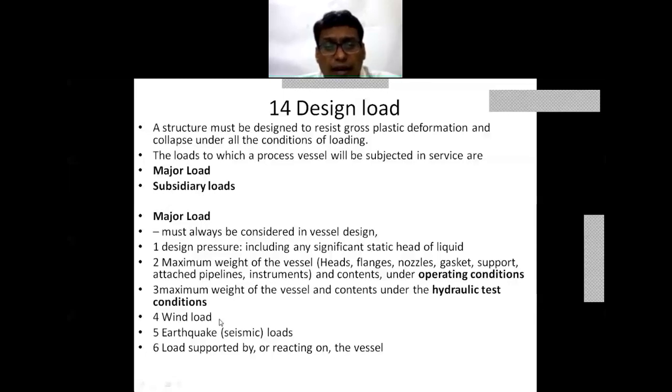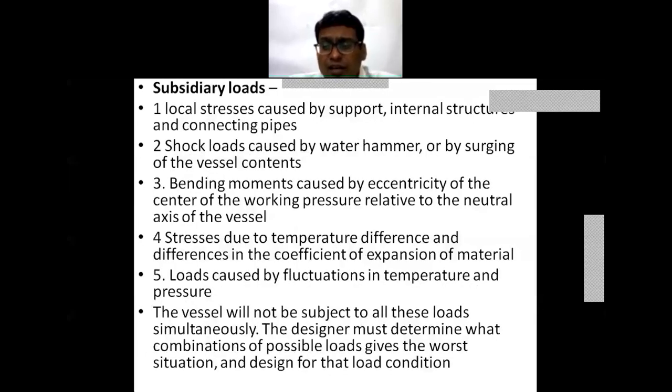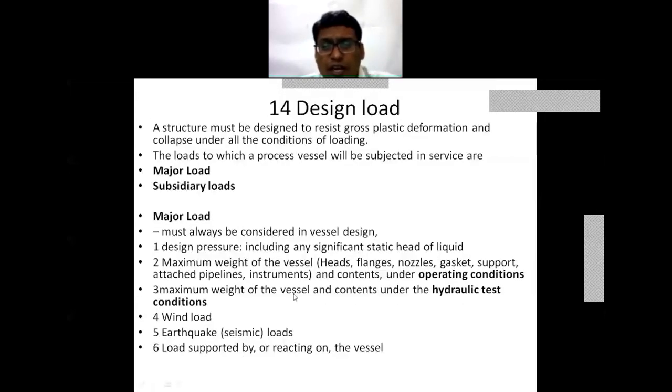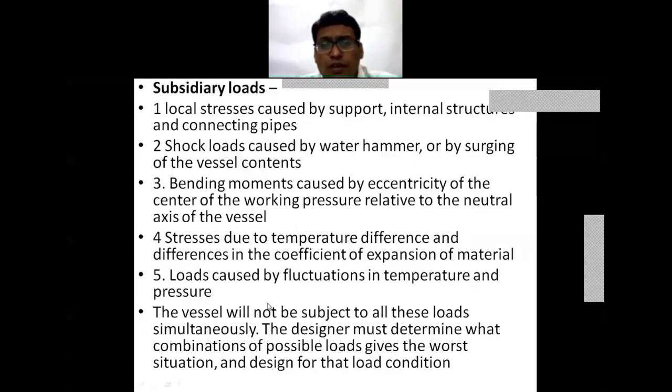So wind load and seismic load and this testing load are also very intermittent or fluctuating. So the vessel will not be subjected to all these loads simultaneously, but the designer must determine what combinations of different possible loads gives the worst situation.